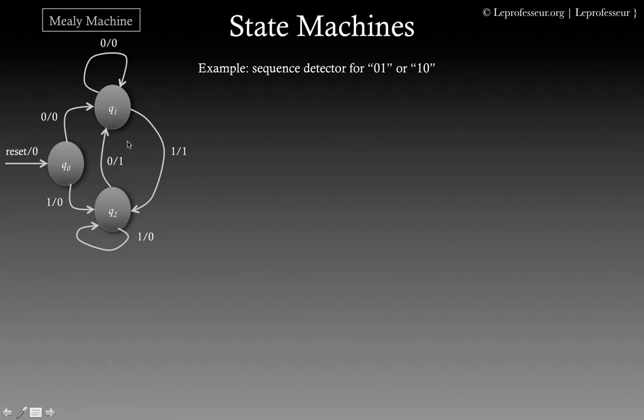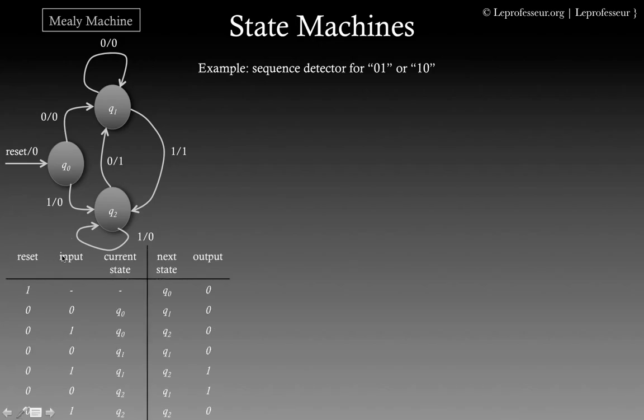Now our objective is to design a digital circuit. So how can we encode these states and make use of flip-flops and combinatorial logic to produce the output? Let's take the next step, that we fill the entries in the state table. The state table is nothing but this graphical representation, where you are just filling up the entries for which state you are in.